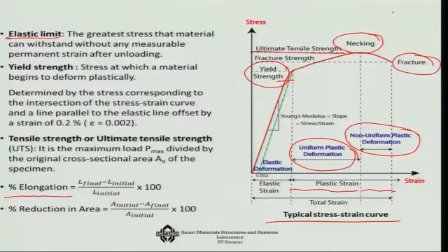I can, in a very small qualitative manner, draw it here, that suppose the stress is denoted by sigma and strain by epsilon. So, if I draw the sigma epsilon for a brittle material, it is just one single line, and maybe some point of nonlinearity, but that is it, and then it sharply fails. That means it will not show any plastic strain, any plastic deformation. That generally happens in terms of the brittle material.